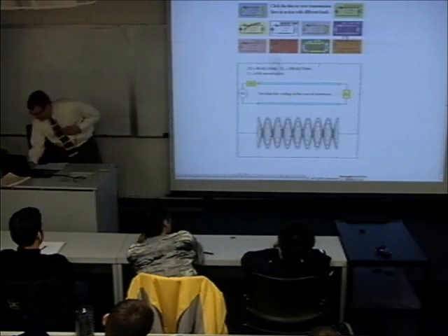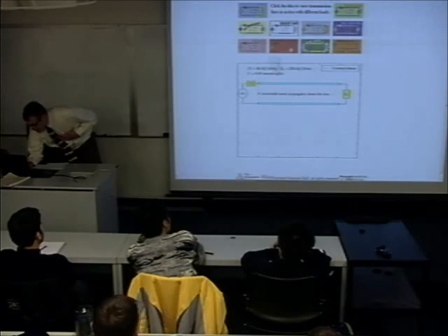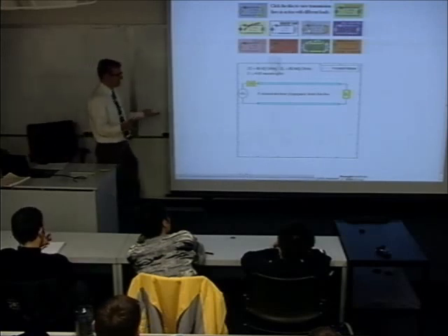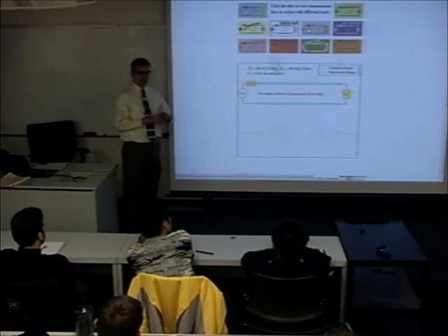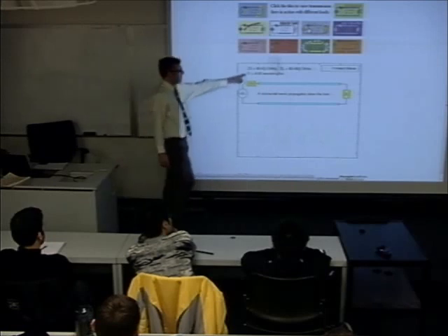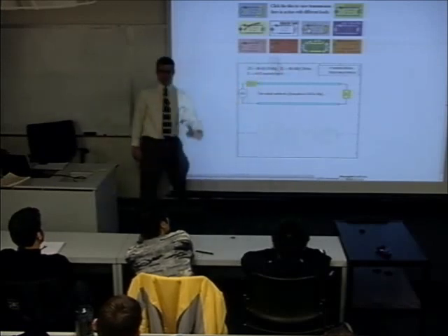So all of those are bad reasons. Now, here's a complex load. Remember what we said last class period: complex loads aren't any different than resistive loads. It means that the reflection coefficient is going to be a complex number, but everything else is the same. It makes a standing wave ratio, and you can see that's probably a VSWR of 2. This is a 50 plus j50 load.